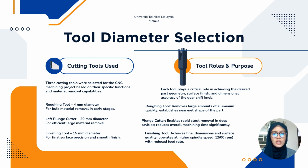P142410265. On this slide, I will explain the cutting tools used in the CNC machining process. Three cutting tools were selected, each with a specific function. First, the 4mm roughing tool removed most of the aluminium material to create the basic shape.